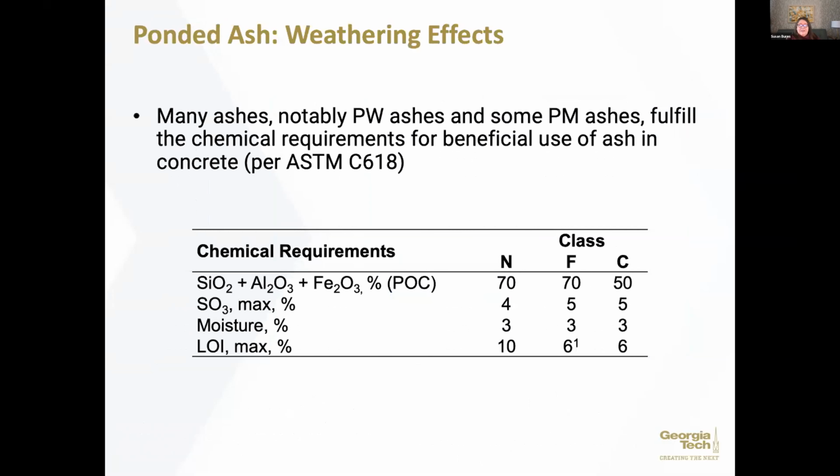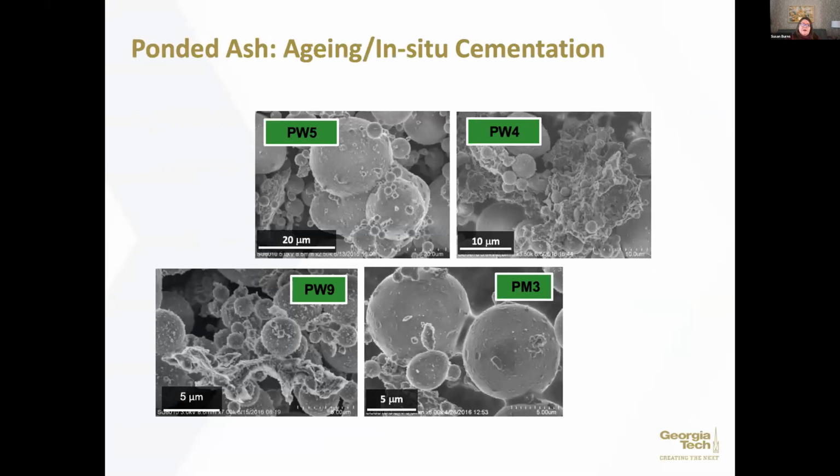Just a reminder to show you that these ashes, in terms of their oxide content, and many of them in terms of their LOI, do meet our standards for ASTM C618 use in concrete. So that's the good news, right? A lot of these ashes have no problem whatsoever meeting those concrete requirements. So these are the ashes that we're going to talk about now.